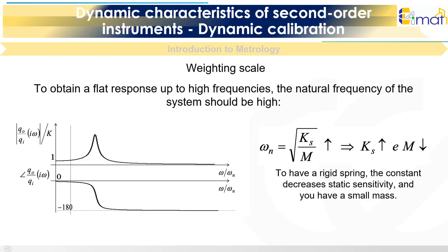To obtain a flat response up to high frequencies, the natural frequency of the system should be high. To have that, you need a rigid spring, but the spring constant decreases static sensitivity, and you need a small mass.